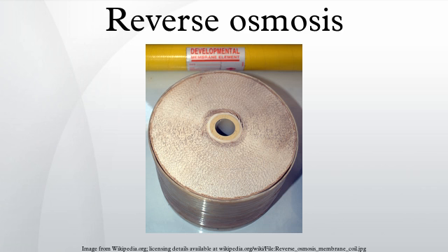These are the simplest energy recovery devices to apply, combining the HP pump and energy recovery in a single self-regulating unit. These are widely used on smaller low-energy systems. They are capable of 3 kWh per cubic meter or less energy consumption. Examples are the Clark pump, the Katadyn desalinators, and the Spectra Pearson pump.